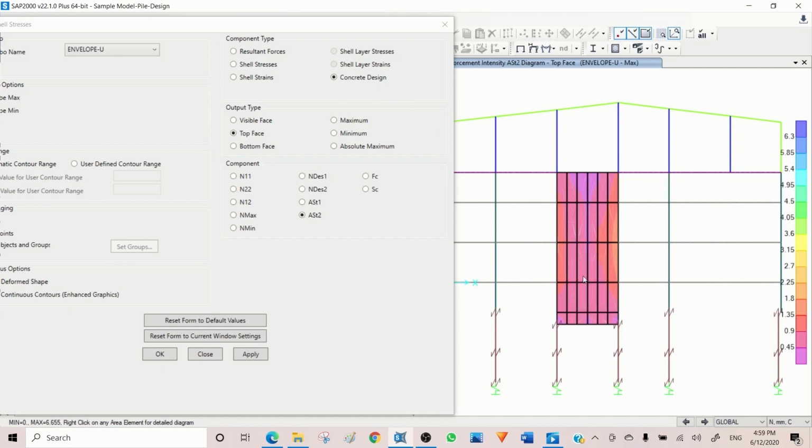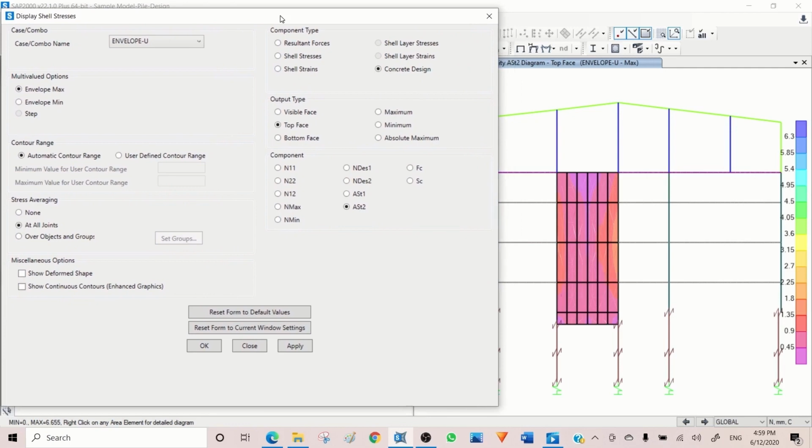So how can I use this one? I want, for example, to have a reasonable reinforcement arrangement here. I want to go for, say, N12 at 200 millimeter. So N12 at 200 millimeter would be 565 square millimeter per meter.